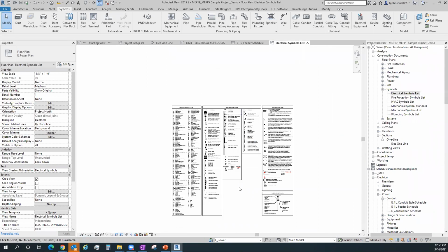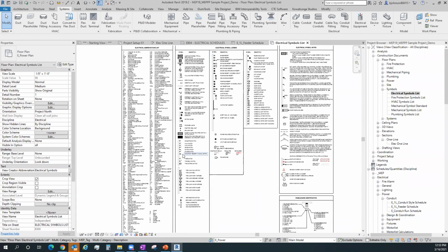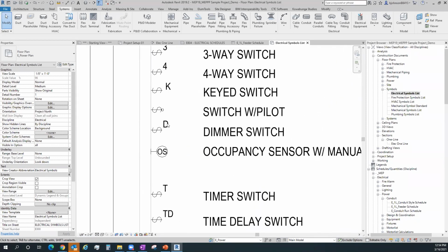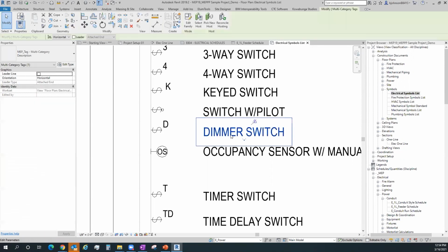3 things, right? Or if I need to duplicate a type and maybe there's a D, an F, a P, and a J on my different types of dimmer switches that are new objects. So I've duplicated them in my family, but then I add them in my list here, change the type on them, and maybe even have a, notice this will be an MEP tag.